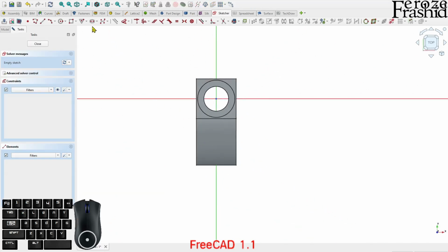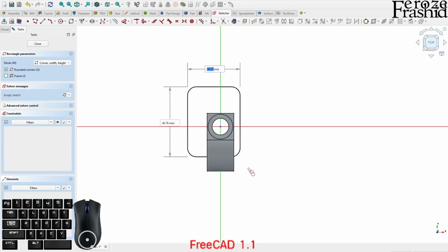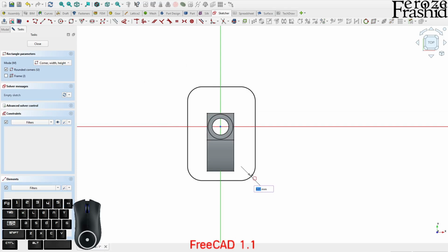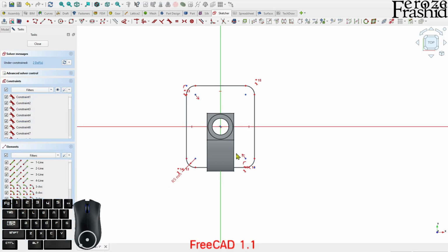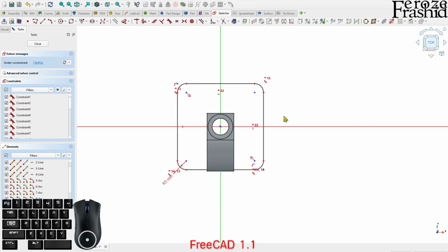In here, so this was 25 millimeter away. So that means we need to do a square, round rectangle, something like this. Let's say the corner is 5 millimeter for now, very sharp corner. And I want to make it symmetric. So take these 2 corners and make it symmetric by the origin, right? And then these 2 edges will be equal because it's a square that we started working off. The distance between these 2, actually, why are we building the whole thing? I want only this corner.